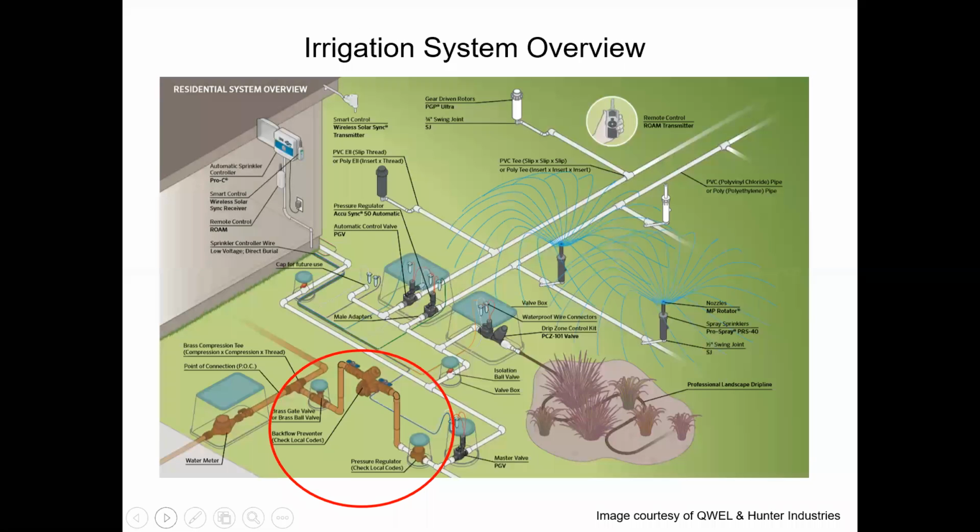So looking at where this actually occurs on your irrigation system, you can see that these are really important components, and they control major features. They're going to occur at the very start of your irrigation system so that you can shut off water if you need to at the very start. The backflow prevention device is preventing all of the water from being siphoned back into the distribution system, and the pressure regulator is regulating the pressure for the entire system.